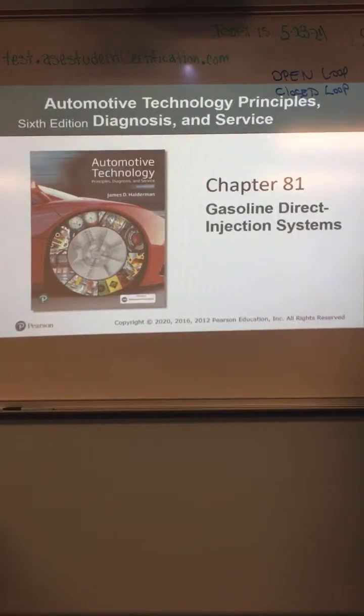Yeah, it should be in here though. It just says voltage applied to the solenoid, but it's going to be your system voltage, it's not a sensor. The only thing that's going to use 5-volt reference is a sensor. Injector is an output, not an input. It's controlled, it doesn't give information.